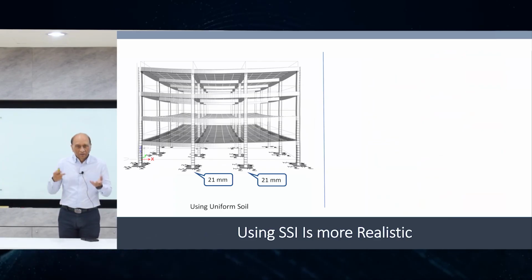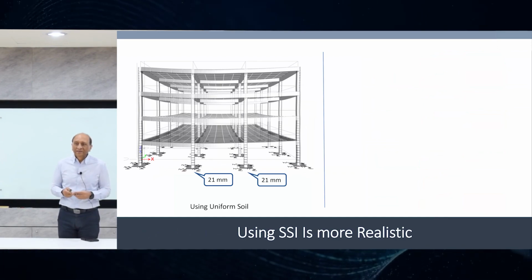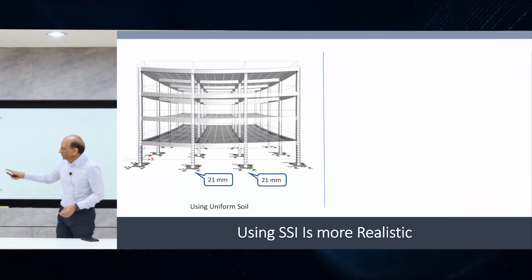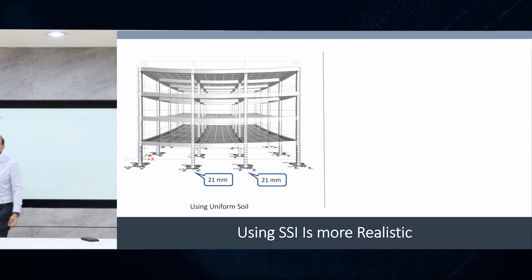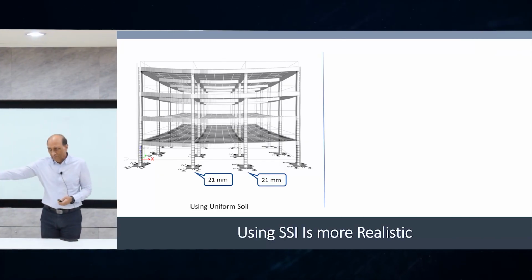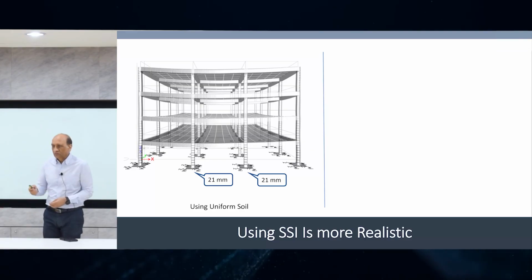Natural settlement of all the foundations was roughly 21 millimeter based on the load and based on the soil properties. Now, let's say one soil that you're trying to say is very, very weak, half the strength. Normal bearing capacity is 1 ton. Here it's only half ton. It can't be less than that, right? So I said, okay, fine, let's try that.